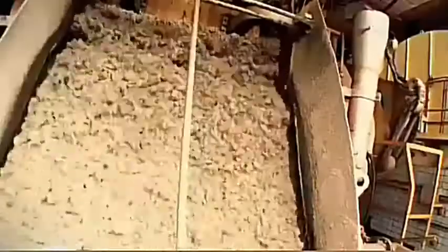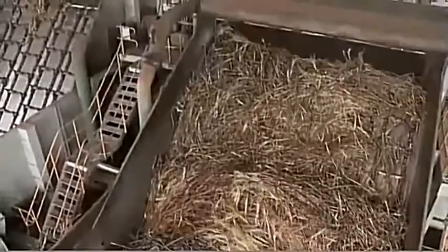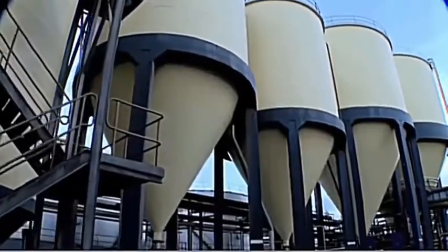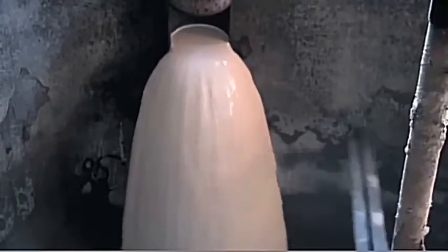After the crush, either by rollers or a diffusion system, what's left of the cane stalk is known as bagasse. The juice that results from the cane crush is used to produce ethanol. Ethanol is produced from sugarcane juice through a fermentation and distilling process. The juice is first purified by various filtering processes until it is ready to be fermented and mixed with yeast.